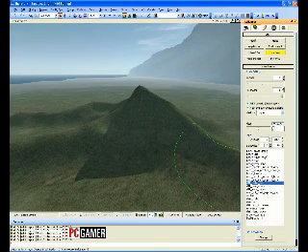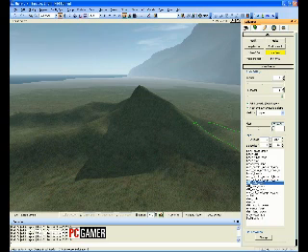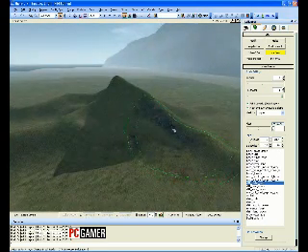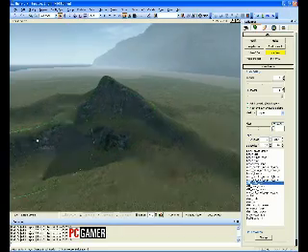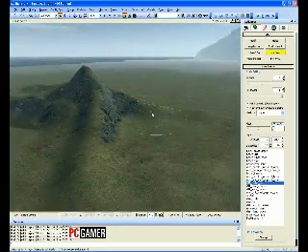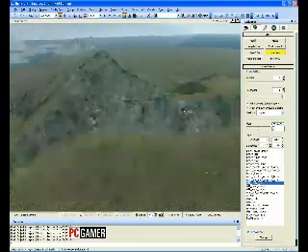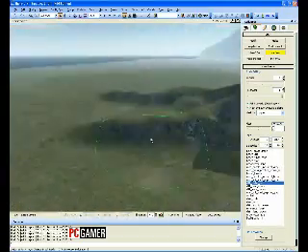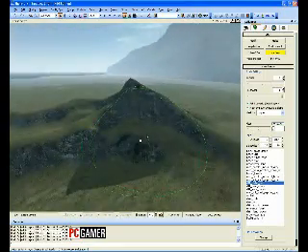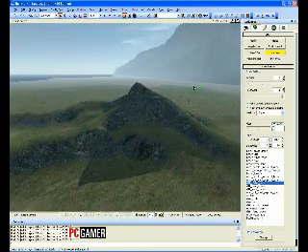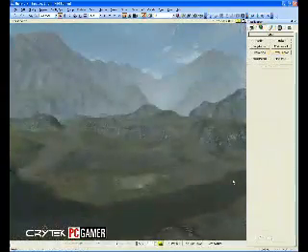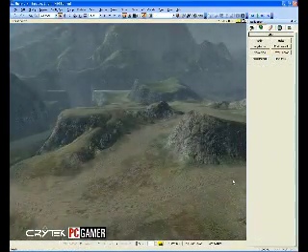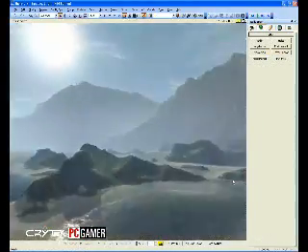For painting areas like mountains and cliffs, it's useful to set up a slope range for your material. In this example, I've chosen a range between 27 and 90 degrees. Now when I paint the terrain, you'll see the texture only appears on parts of the terrain sloped within the angles we previously defined. As you can see, this makes terrain painting very quick and easy, with great results.